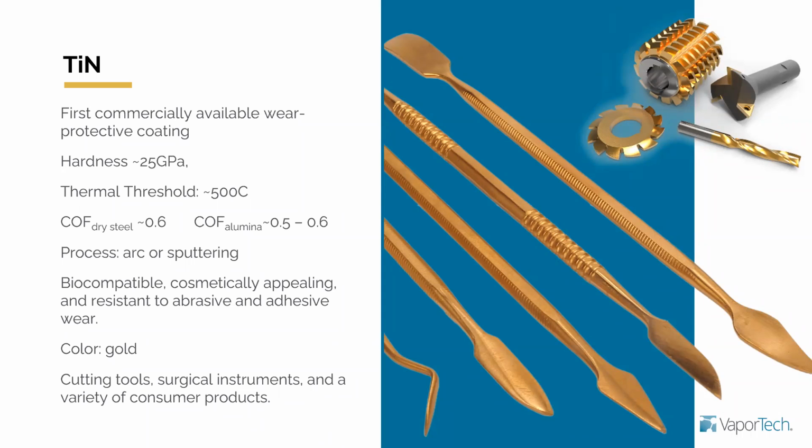Right? So it does have very high hardness as well, which is a common theme for all the coatings that we're talking about. Very good thermal threshold, 500 degrees C, which is pretty much about the limit that you're going to find for some of these tool steels that are available. And again, the way we gauge that for a steel or a substrate is what's the tempering temperature.